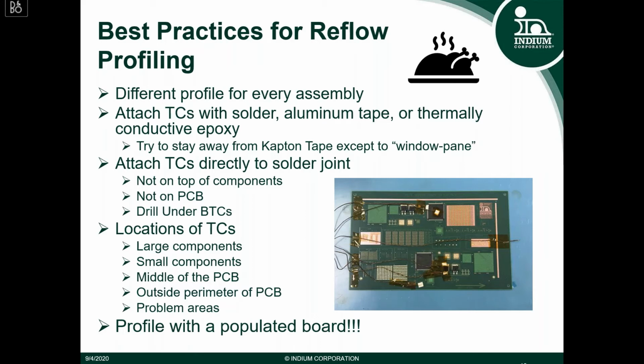For every assembly, a different profile should be conducted, because every assembly has a different thermal mass: the board's thermal mass, the component's thermal mass, the component density on the board. Each assembly is unique and different and deserves its own reflow profile.